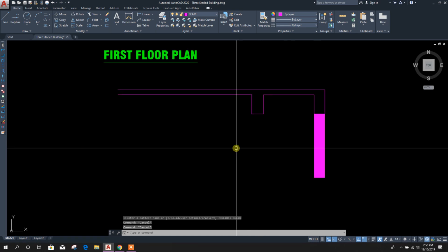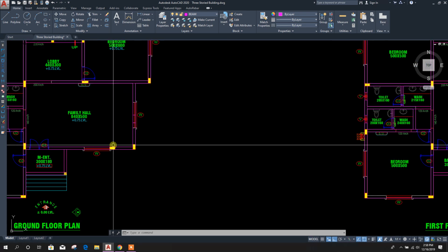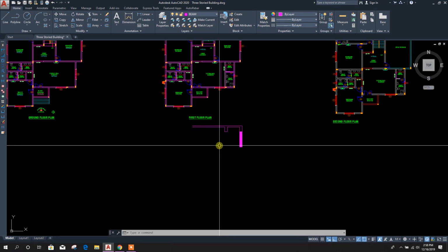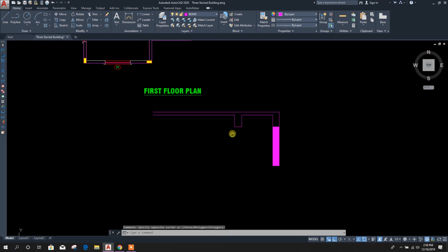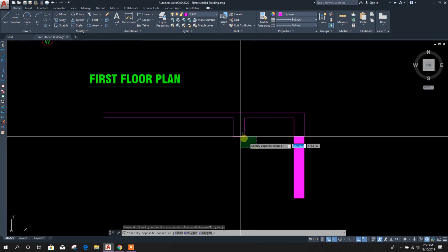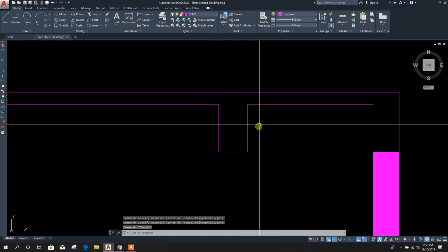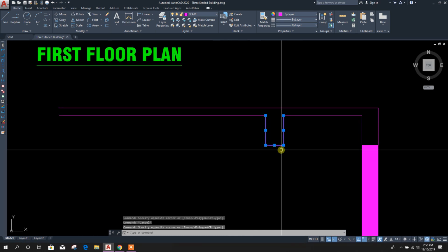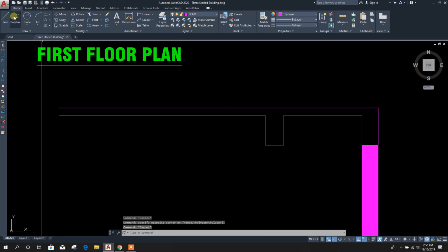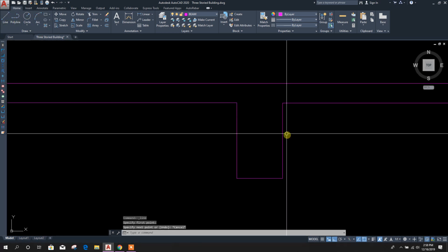So but at ground floor, here in this position there is no wall. So from ground we can see this beam is hanging. So to avoid this offset from slab, or to avoid this odd looking beam, we can provide hidden beam like from here to here.